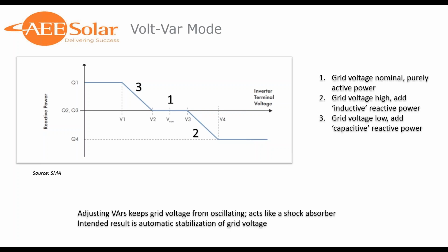That's assuming, of course, that your local utility district hasn't required you to use some bizarre constant power factor. Volt VAR mode should override those constant power factor settings. So if they've specified a constant power factor of 0.95, but they've done the set points right on volt VAR mode, if you are outside of that voltage window, the power factor will adjust. So interesting stuff, and I'm looking forward to seeing some studies on how this actually helps support some of these small, less resilient grids.